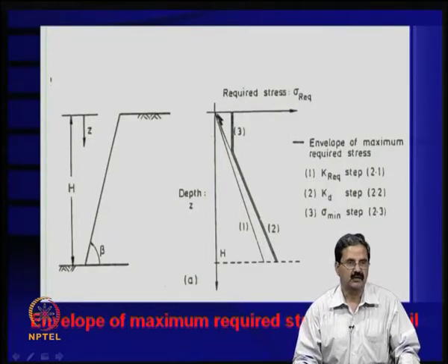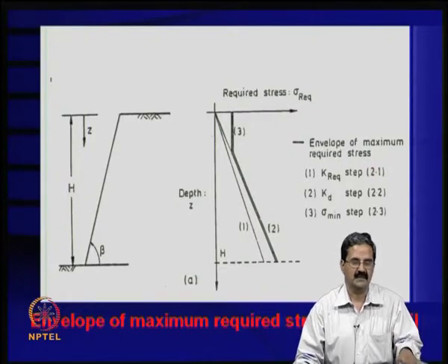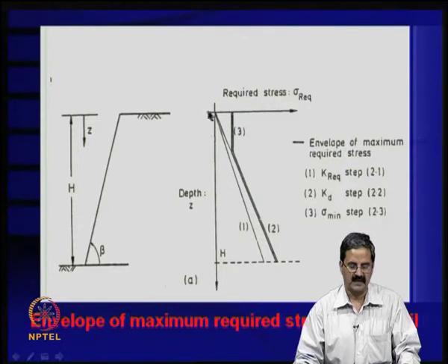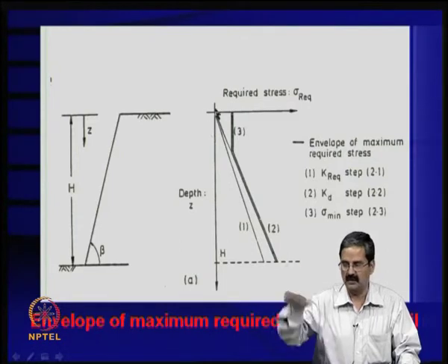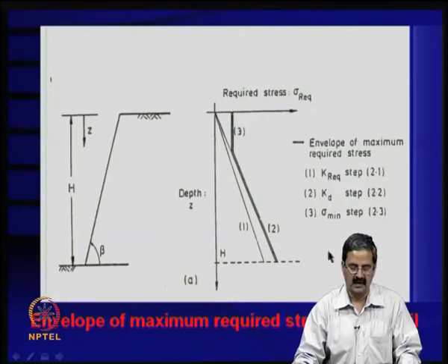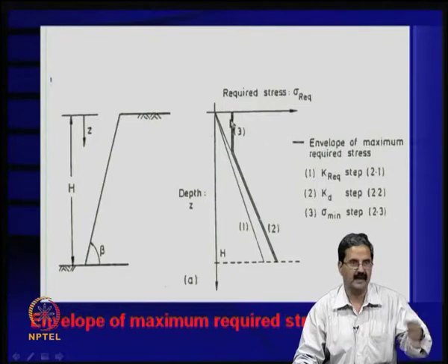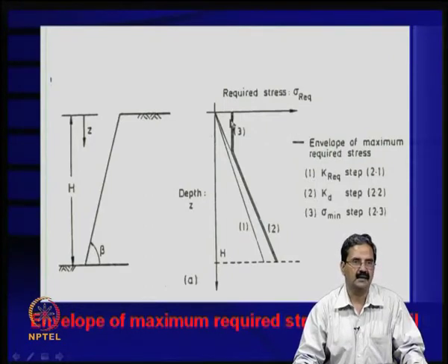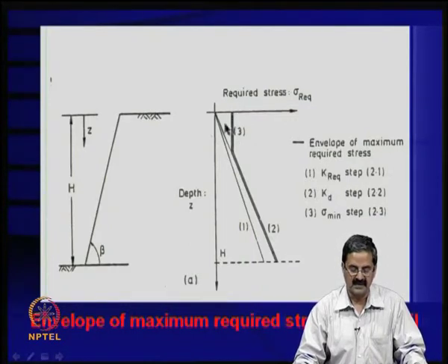Why? Because you have compacted it, and there is always some sort of earth pressure for which it has to be designed, because earth pressure is never 0 at the top. Actually we do not really compact heavily; we use simple compaction equipment like hand-held equipment, and some compaction stress is induced.